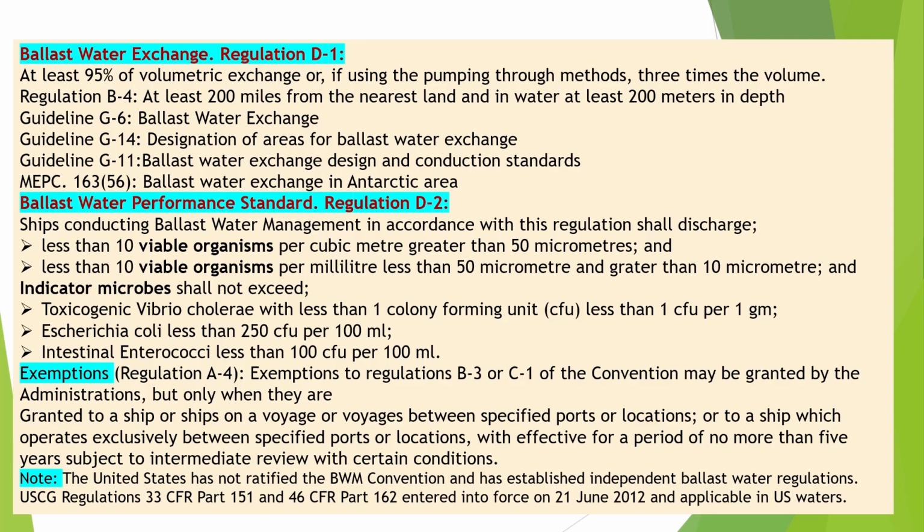Ballast water exchange. Regulation D1. At least 95% of volumetric exchange or, if using the pumping through method, 3 times the volume. Regulation B4, at least 200 miles from the nearest land and in water at least 200 meters in depth.